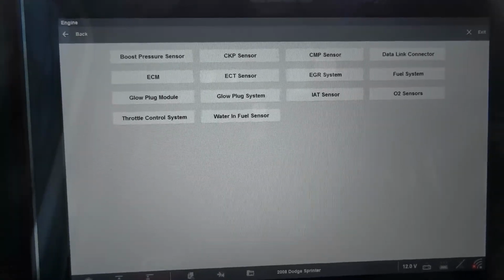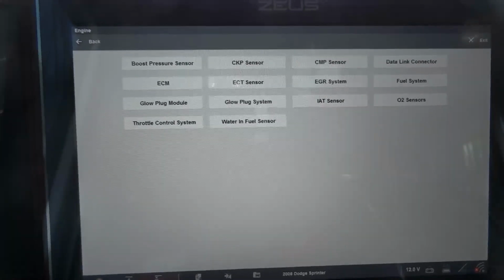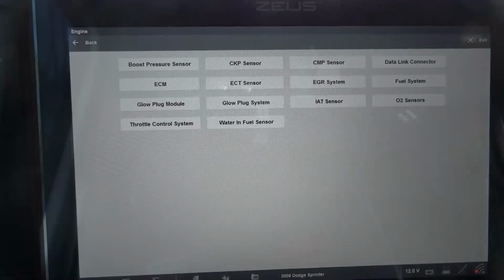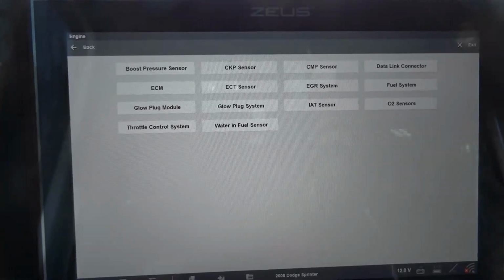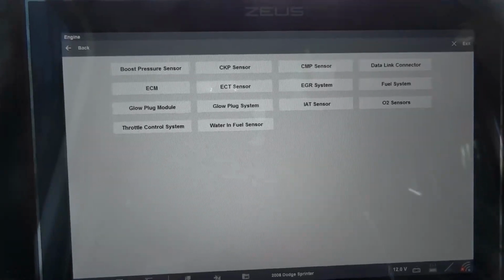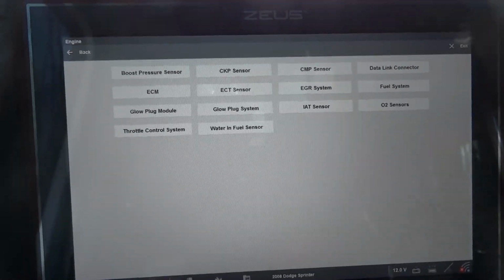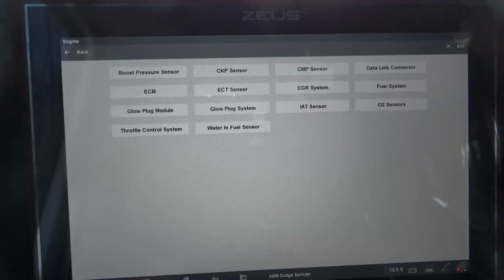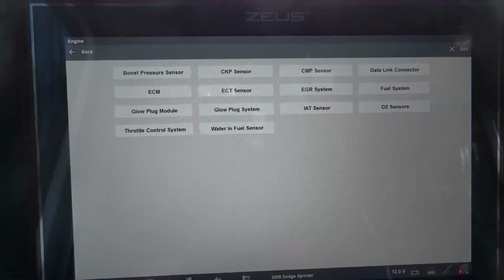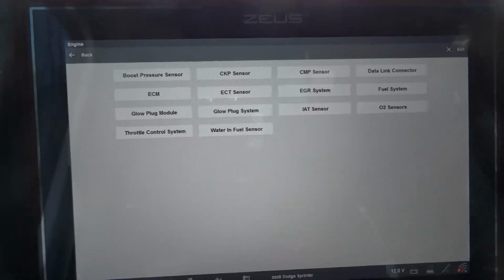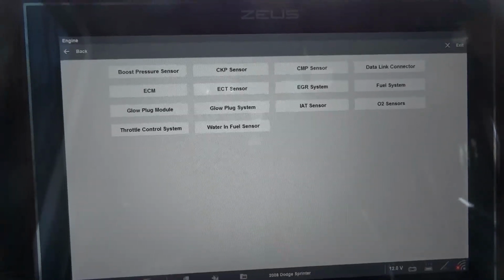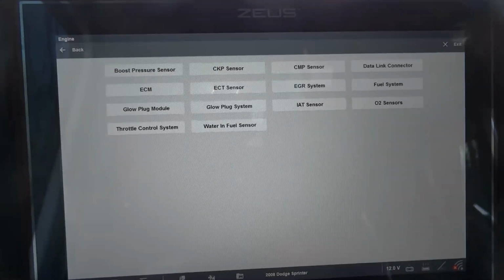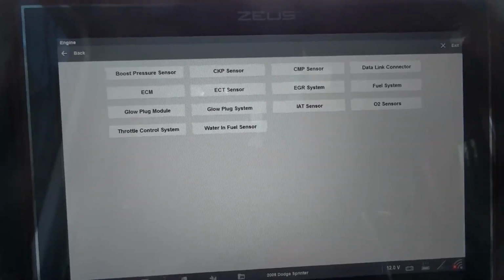So I would like to see how this sensor is wired, but I can't access my wiring diagrams right now because I want to know if this sensor receives its power feed from the computer or from a fuse, because I know some Hall effect sensors, I mean, I'm pretty sure this is most likely a Hall effect sensor.